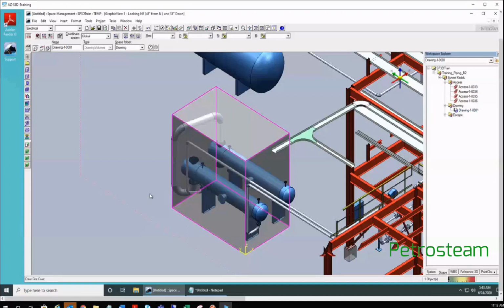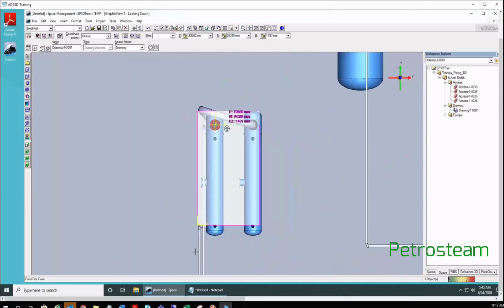Now you are allowed to modify this point. The second point is fixed, and the first point is moving here and there. Let us go to top view and see. Maybe easting 21500 will work for us. F6, 21500. And northing, as you can see in the top, 19 meter should work for us.